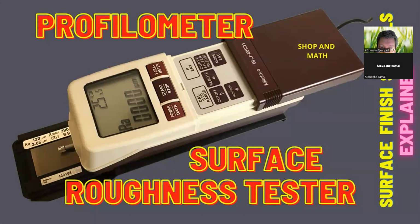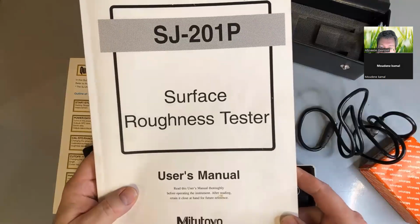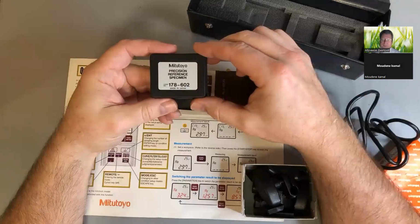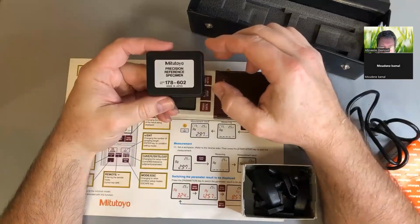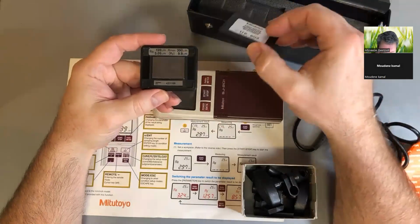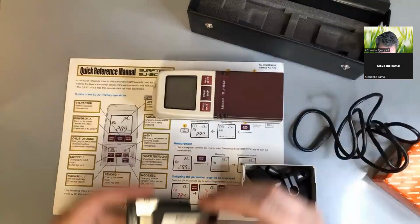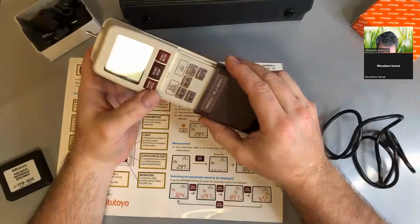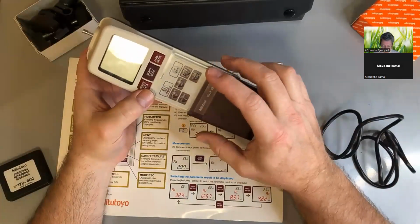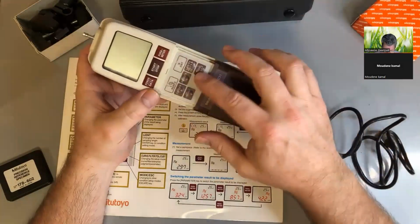Profilometer or surface roughness tester. So why do I keep calling this a surface roughness tester? Because that's what Mitutoyo calls it. This also comes with a precision reference specimen. If you looked at this, we used this earlier today when we calibrated the machine. For extra references and zeroing and changing the different parameters, we use these buttons here.